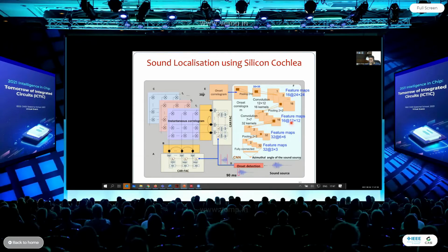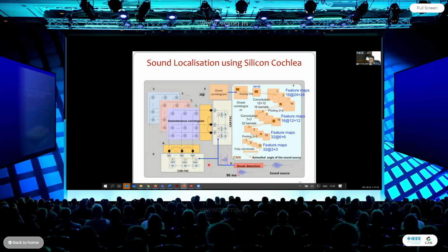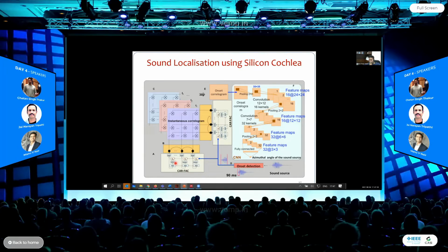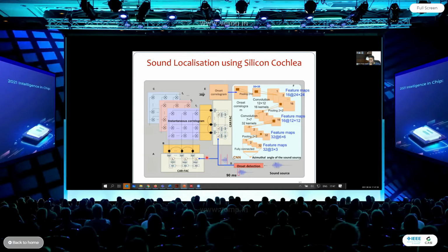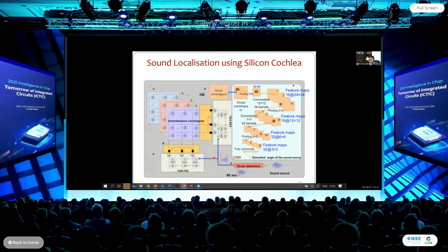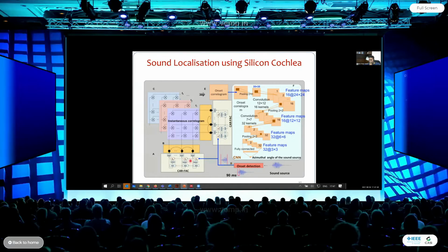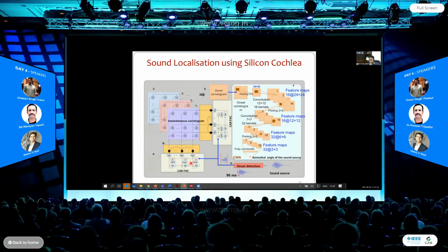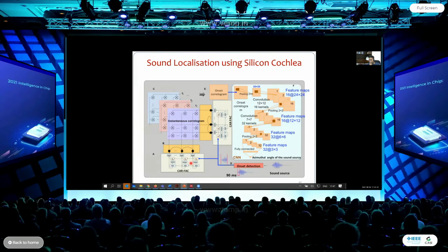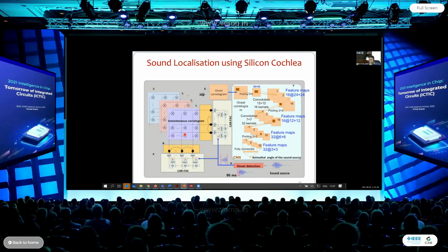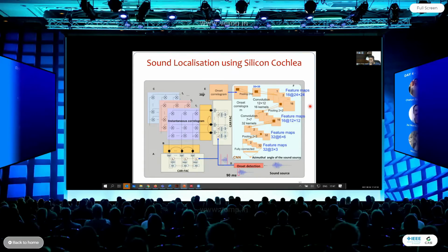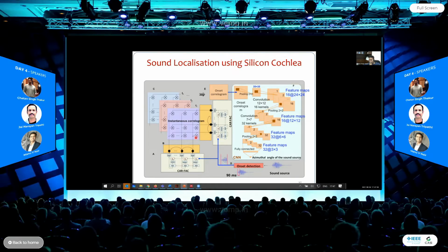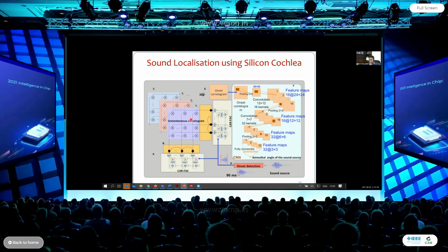Here we use 70 channels instead of 100 channels, which means 70 cascaded filters to pre-process the binaural signals. This cascade structure acts as a delay line, and that's how it is useful when you do the correlation across different channels, right? So we have 70 channels here, 70 channels here, and then we do this instantaneous correlogram.